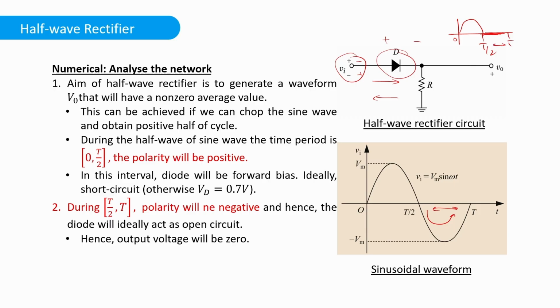Now when this signal starts to extend from this point, once again we will have output voltage, because it again enters the positive region. But once it later enters the negative phase once more, at that point we will again have no output voltage. So actually, the output voltage will have these kinds of ripples, or you can say fluctuations. We will have output only during the positive half cycle of the input voltage.